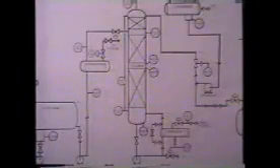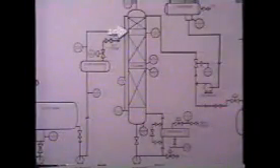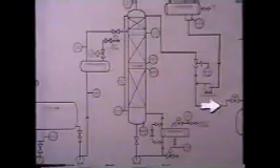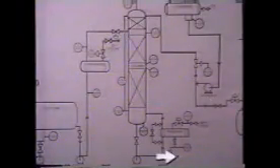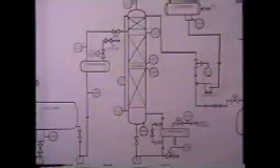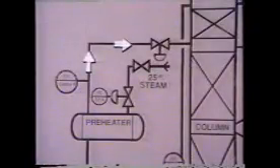The basic goal of a short-term shutdown is to stop feed to the column and stop the overhead and bottoms product takeoff. The majority of the equipment is kept in operation so that the system can be restarted quickly. In the first step, the inside operator shuts off the steam to the preheater by setting the preheater temperature controller to 0. This removes heat from the feed mixture.